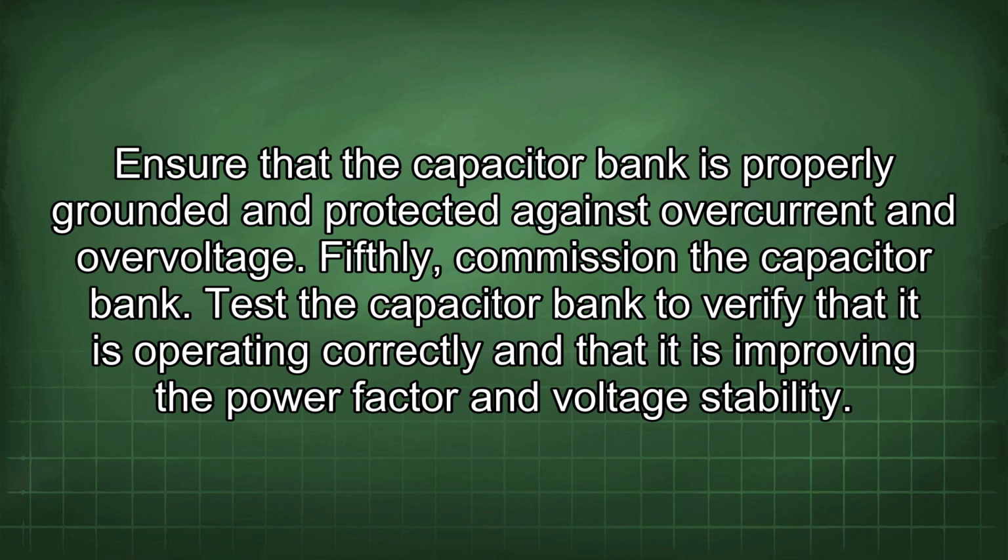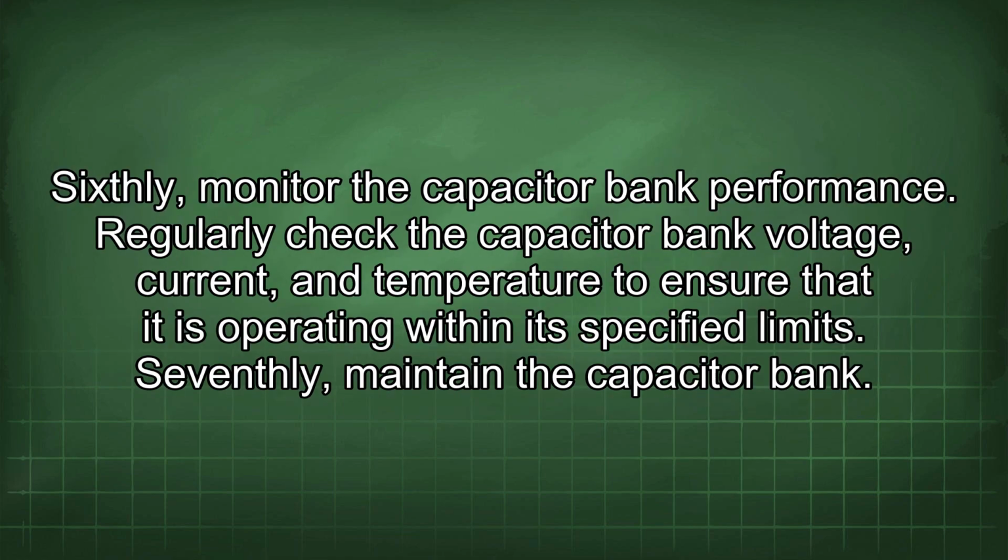Fifthly, commission the capacitor bank. Test the capacitor bank to verify that it is operating correctly and that it is improving the power factor and voltage stability. Sixthly, monitor the capacitor bank performance. Regularly check the capacitor bank voltage, current, and temperature to ensure that it is operating within its specified limits.